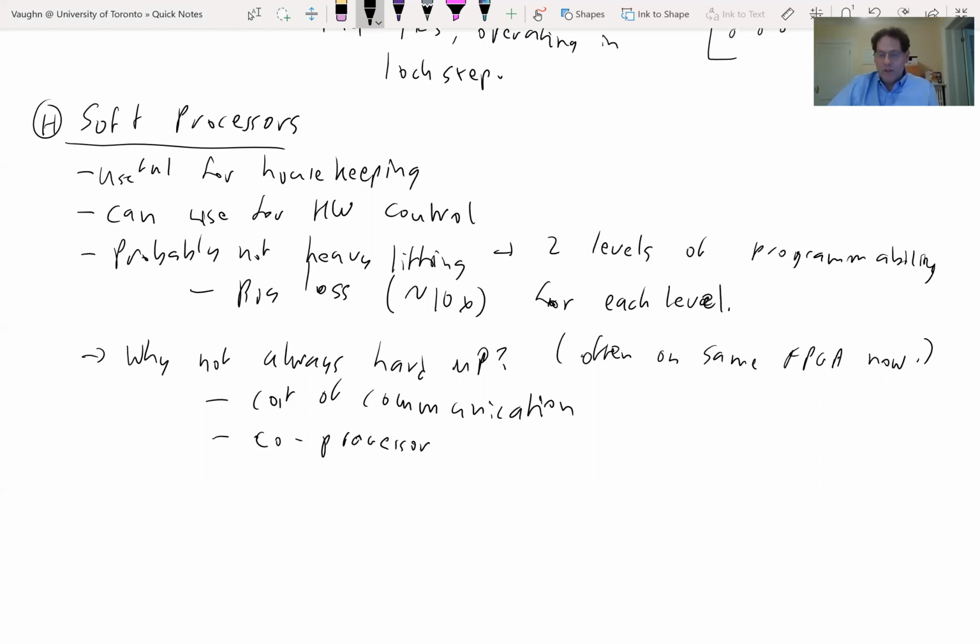You can for sure do that with soft processors. You've got one hard processor subsystem, so it might not be the most convenient. It might take too many clock cycles for the data from the processor to get there. You may not have exactly the wires you'd like coming out of it. You may not have enough of them. So when you're controlling hardware units, that's another reason.